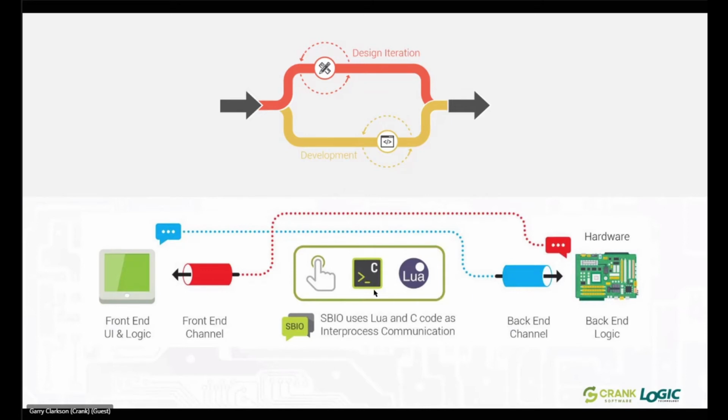So this is something called Storyboard IO, an inter-process communication mechanism within our architecture, which allows you to basically separate the front and the back end by these message queues. And that allows you, for example, and this is very popular with a lot of people, to develop and test on the desktop and then deploy by literally copying it to the target. So we don't generate code, we generate a model and a model view controller. And that allows you to really test things on the desktop environment, do the translation, do the scaling up, the scaling down, do all the user experience with the designers tightly involved in that, and then deploy often and easily to the target to see what it actually looks like when you're using a real thing.